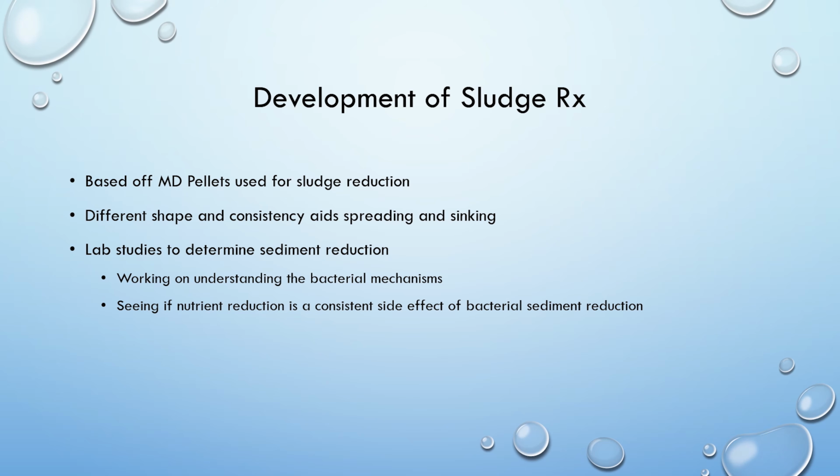So we developed Sludge Rx based off of our successful MD pellets that were also used for sludge reduction. The Sludge Rx tablets have a different shape and consistency compared to the MD pellets, and this aids in spreading and sinking. We have performed lab studies to determine sediment reduction using Sludge Rx, and we are working on understanding the bacterial mechanisms in biological sludge reduction. We are also examining whether nutrient reduction is a consistent side effect of bacterial sediment reduction.